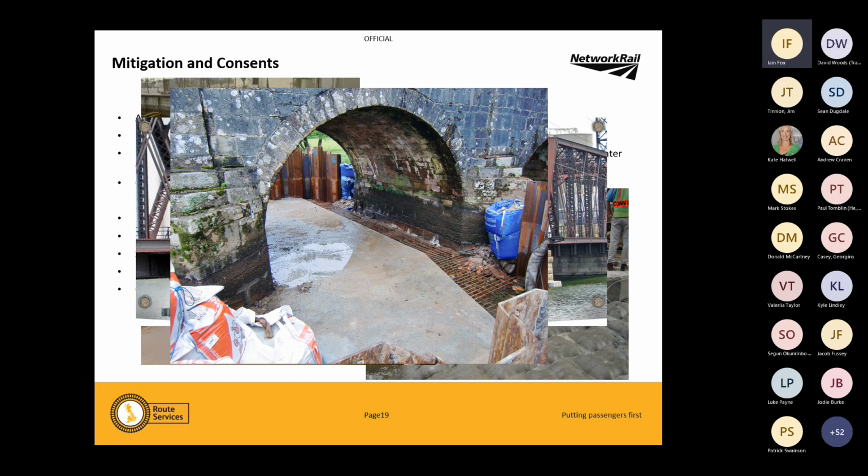I'm terrible for it. And then we've got, as we've said earlier on, the concrete invert. So that's very straightforward concrete, pour some reinforced concrete, some 393 mesh or whatever it is underneath it. But you have to have that transition material, otherwise you're going to get damage.